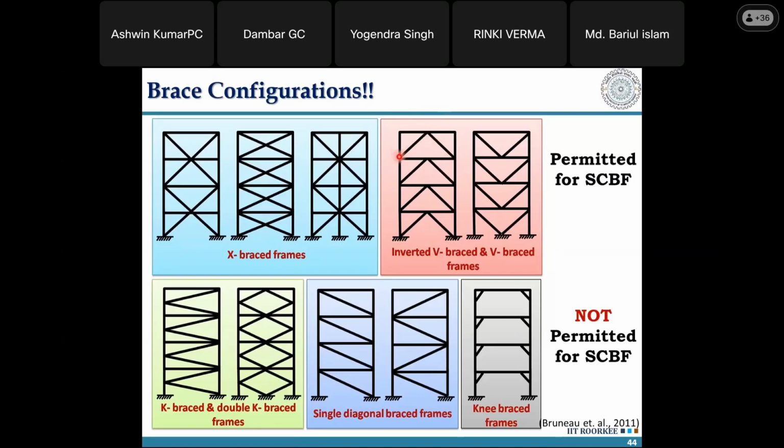So if I model this system like this itself, I might be getting an advantage in the beam size, saying that this is getting supported at this location. The chevron arrangement is supporting the beam at the mid location, so my span of the beam is getting reduced. But what you have to understand is, even before or after the entire design, what you have to ensure is, do not take the advantage of the chevron arrangement or the inverted V arrangement in any case for the beams and columns to carry the gravity load.